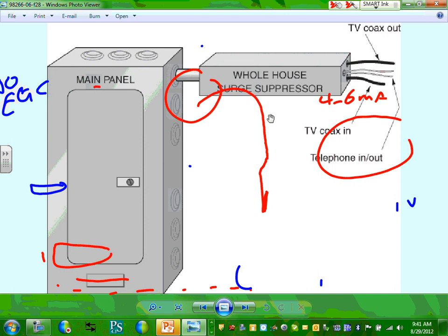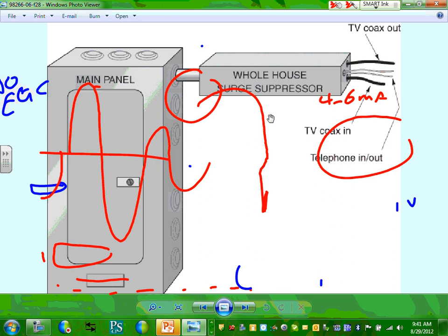So in surge protection, there are lines of defense. Line number 1 at the service, line number 2 at the sub panel, and line number 3 right at the device. Here's the surge, and this is my nice voltage. At the service, they cut this. Then downstream at the panel, they cut a little bit more.